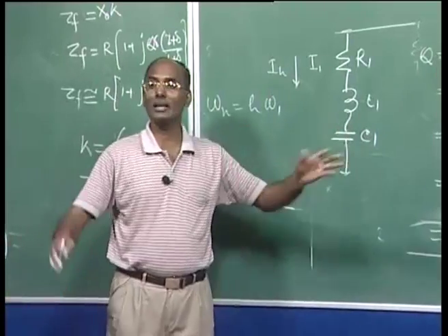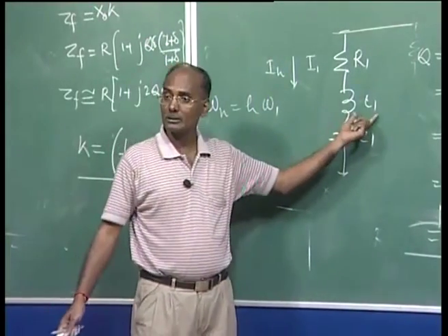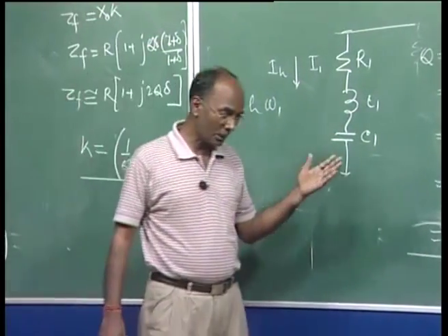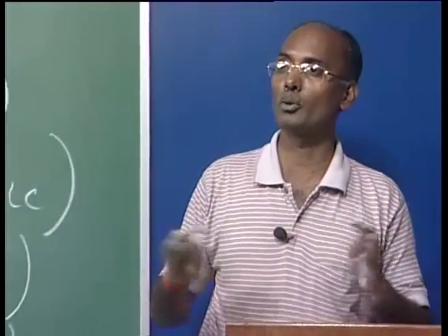The inductor is bigger than a transformer, because the value of this inductor is required for the particular harmonics, 5th, 7th, etc. And if you are going for higher and higher harmonics, the size of these filters becomes more and more larger.